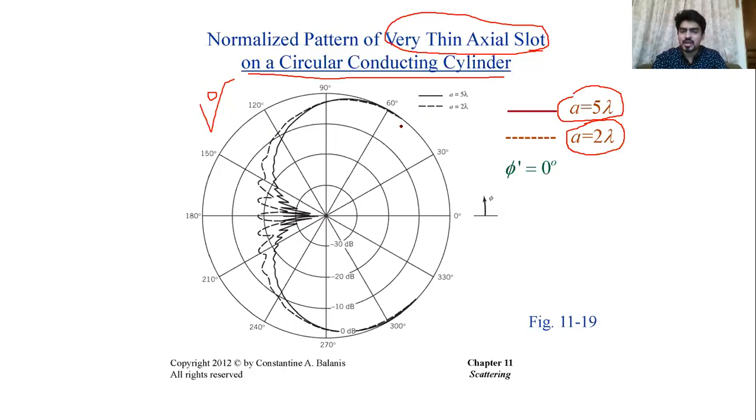So what happens is, this is the location of your aperture. This is a slot here. So there are some waves which are getting radiated from this slot, and along with that, some waves are going to travel along this surface, and when they travel along the surface, they will continuously lose their energy by radiating some waves, by leaking some energy.